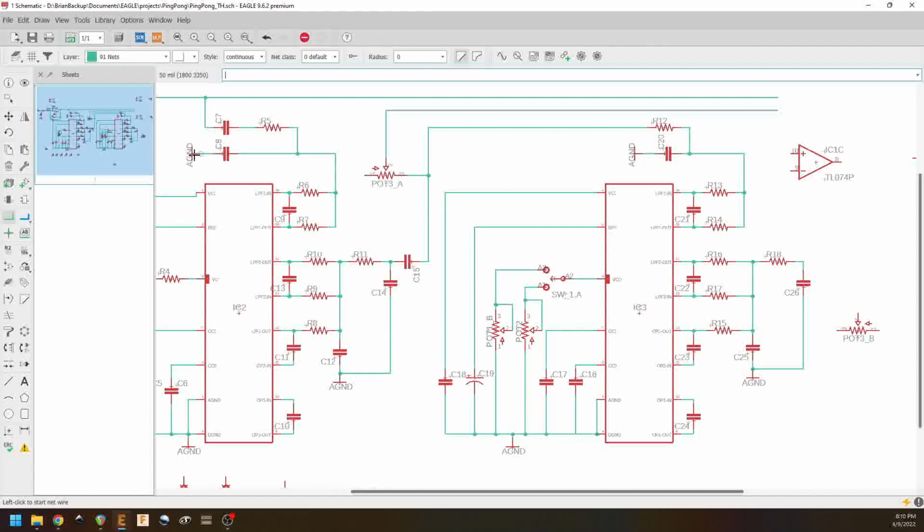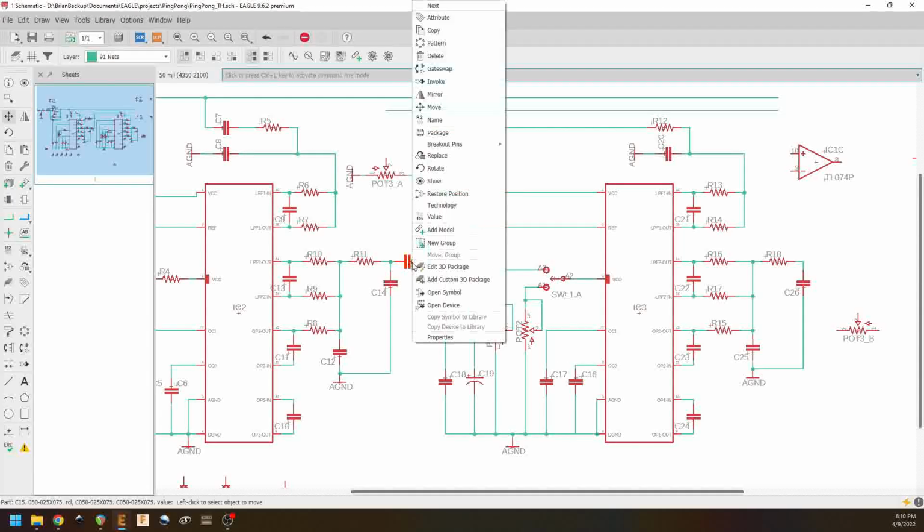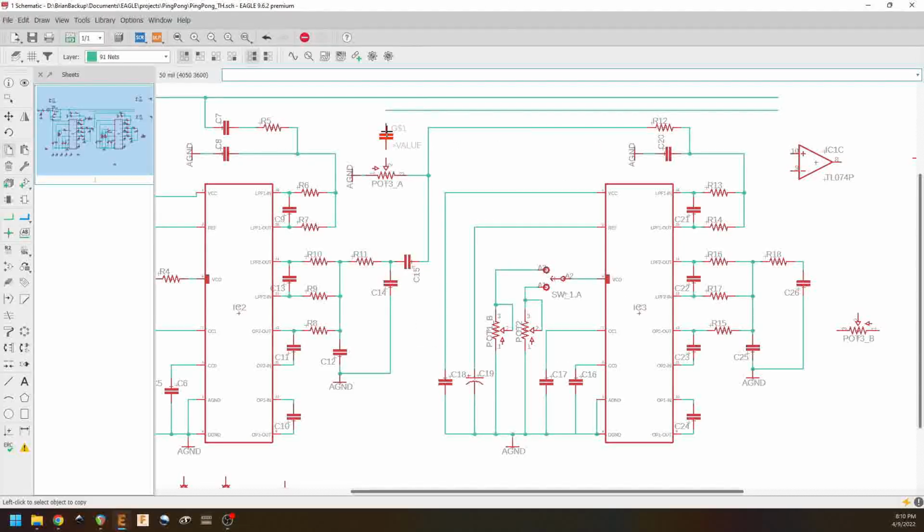And then, oops, there we go. We're going to have ground connecting lug 1 of this pot. Okay. Actually, just for the sake of good design, and maybe possibly overkill, we're going to make sure that we have a DC blocking cap here, just to make really super sure that nothing's going to come in on here and mess us up. Okay. All right. So now that we've got that mix control going on,